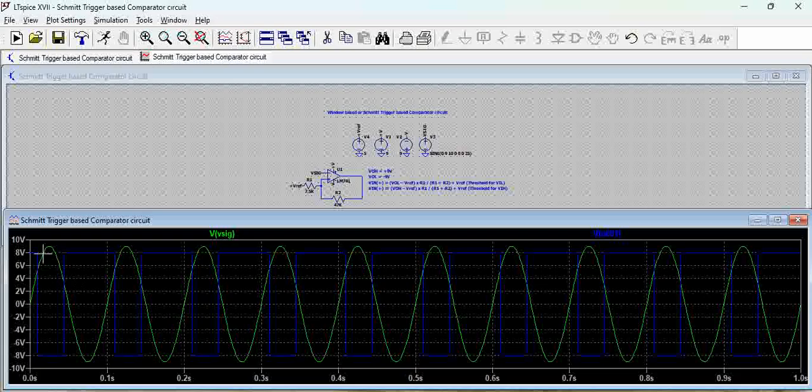So now what happens is when it goes low beyond 3.3 volts, only then does the output go high. You can see here the blue line goes high. That means the inverting terminal voltage has gone below a specific voltage on the non-inverting terminal, so that the output is high because the non-inverting terminal voltage is high. So that is how the comparator works, right? With this band, this particular 5.5 to 3.3, you actually see that the comparator doesn't respond to the input voltage, and it remains at a fixed level.